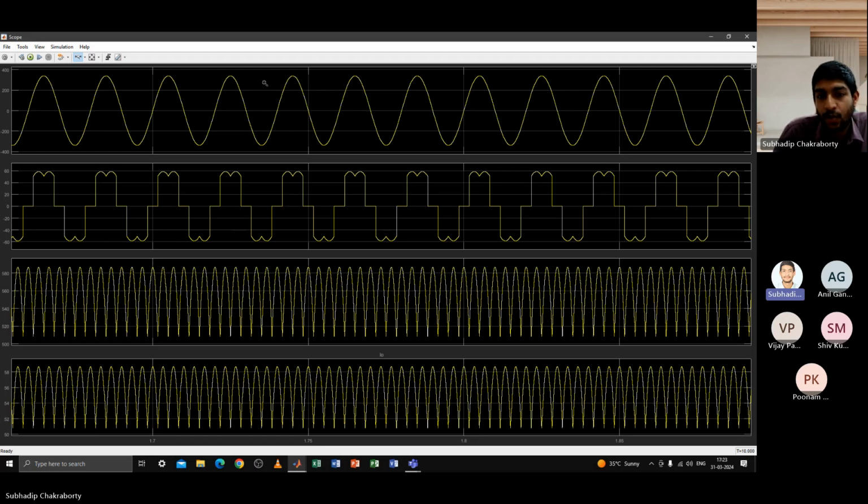But if I now tell you the load has changed, the harmonic nature of the load current has changed, and accordingly your targets have also changed, then similarly for the harmonic components you will just provide the low impedance path for those harmonic currents, and their amplitudes may also vary. So then the amplitude of the filter current will also vary. Then the rating of the filter current will also vary. You understand my point, right?